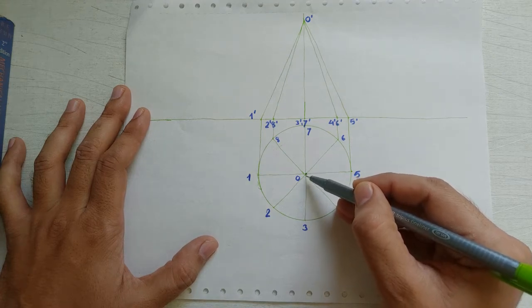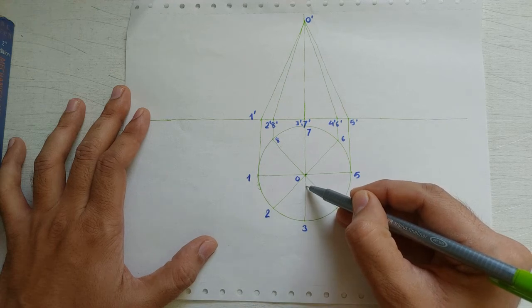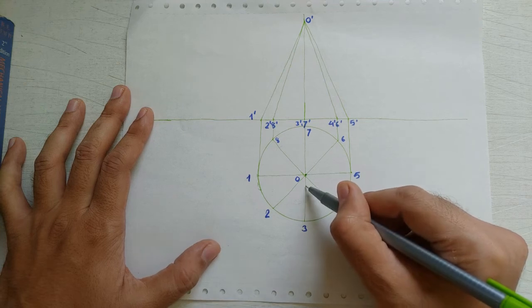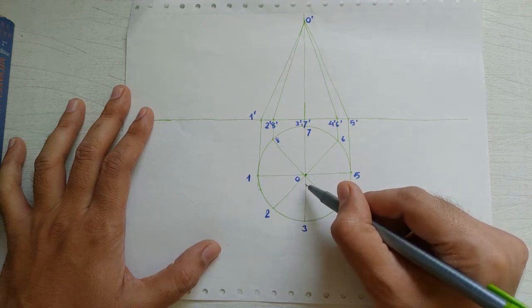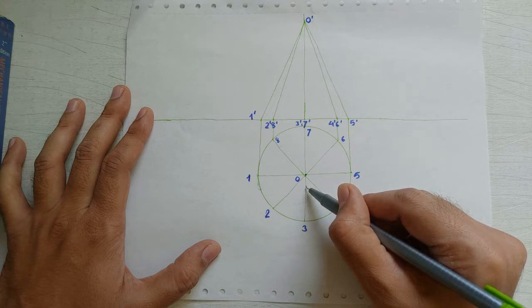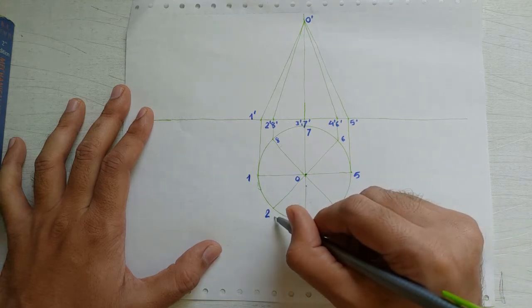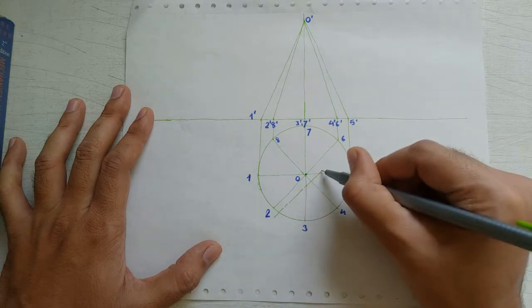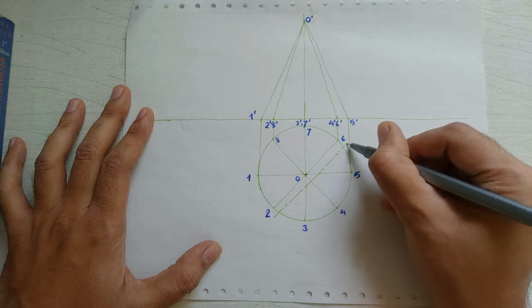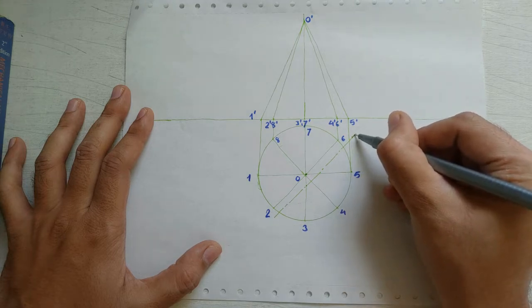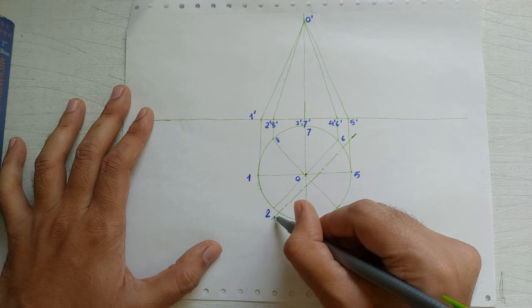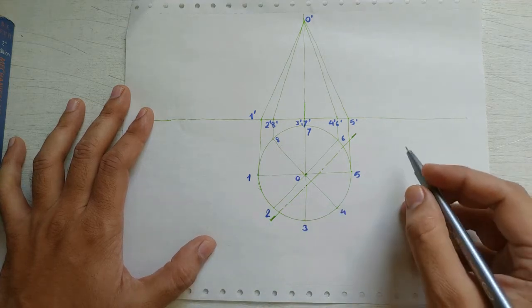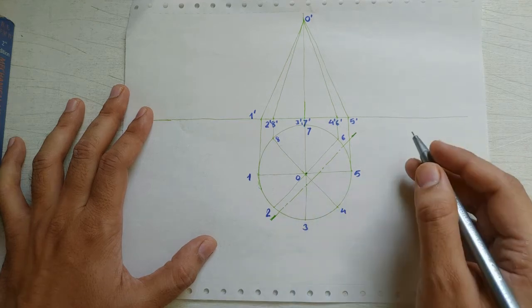So we will measure 10 mm from this point and mark a point here, and then we will draw a line of 45 degree passing through this point, and that will be the cutting plane. So basically we are drawing a line of 45 degree here, that is a chain line with thick ends which represents the cutting plane. Okay, so now the cutting plane is obtained.